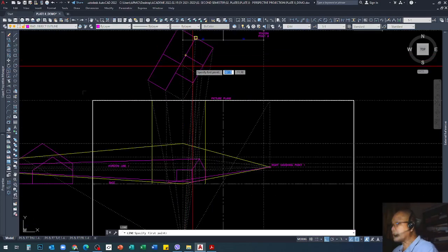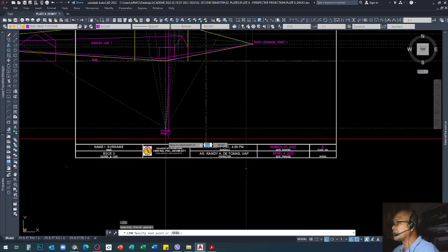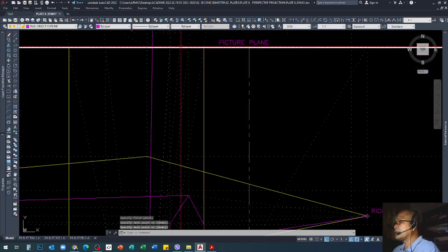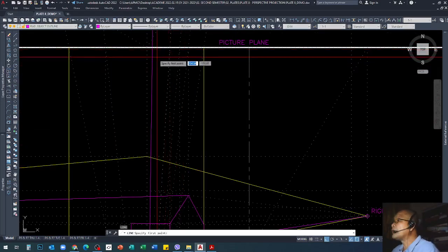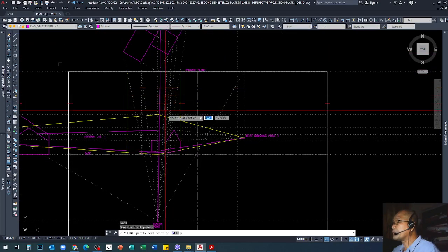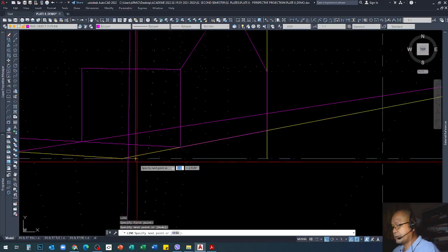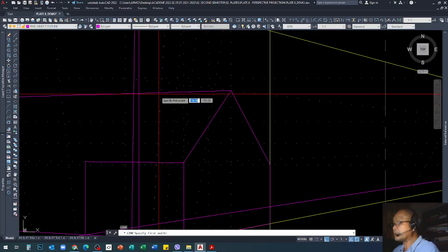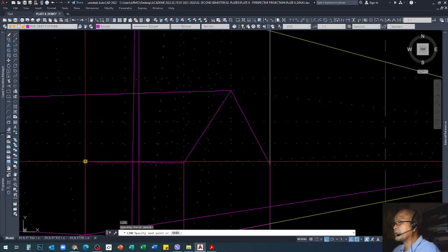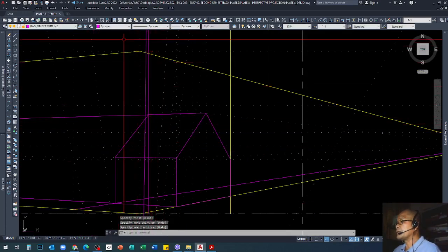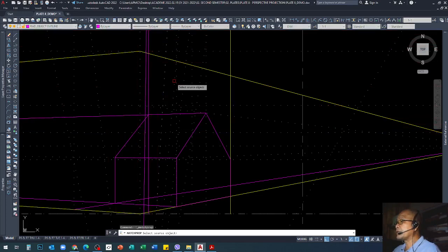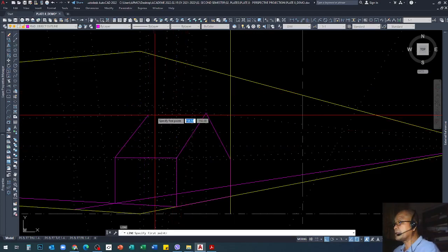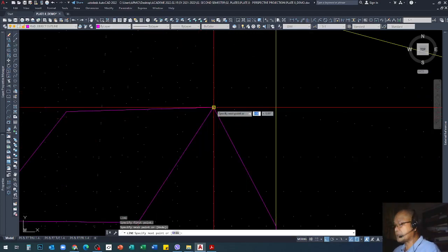You can project another line to your vanishing point. Okay, and when it touches your picture plane, draw a vertical line, and the line that intersects this projected line will be the tip of your sloping portion. So after that, convert your guidelines into dotted lines, and then complete it with the continuous line using